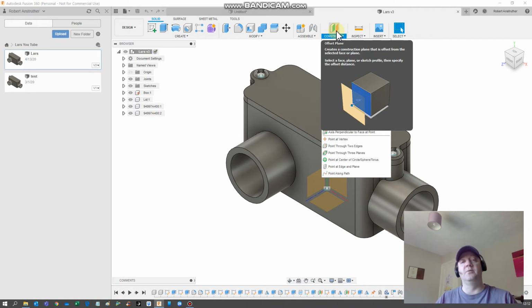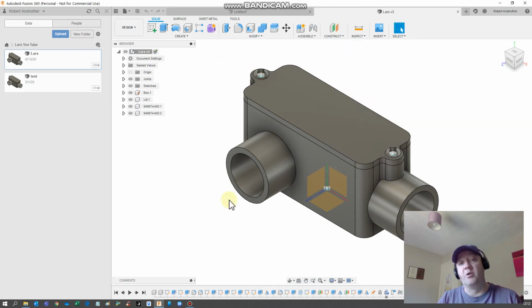So if you think about ribs or profiles of a model that we normally use, they're spaced out kind of equally from front to rear. Each one of those would represent a plane that you're going to draw on, basically. And actually, the way I've done my modeling is very similar to how we model today in Balsa. You create your profiles, you separate them out, and then you link them up with a tool called Lofting, which is really basically putting that blue foam in there, but making it perfect without you having to cut it or sand it already.